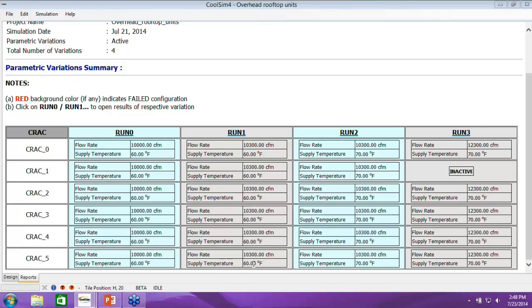So I brought it up 1,800 CFM roughly, 300 each, to try to improve that. And then I started marching up the temperatures, right? Same as before, same methodology. Get RTI set, then start marching up the hill of temperature of supply air temp.